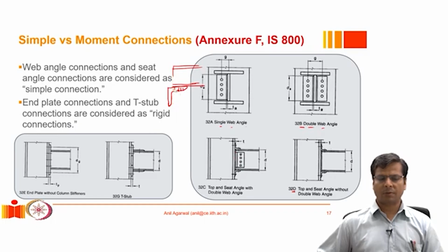Also, in order for it to be able to resist that moment, we may use more than one row, at least 2 rows or more than 2 rows of bolts if we are going to use bolts, or a deep connection, a long weld, so that it can effectively resist that eccentric moment because of the eccentricity of the load. The effective load is acting here, whereas the connection is actually here, so there is an eccentricity that needs to be resisted effectively.